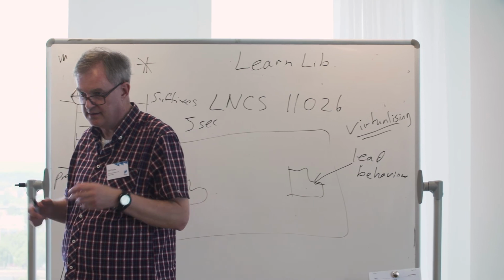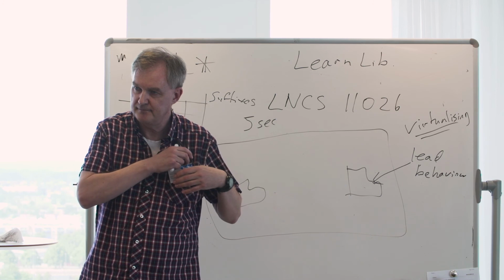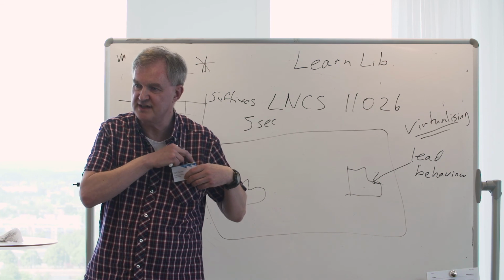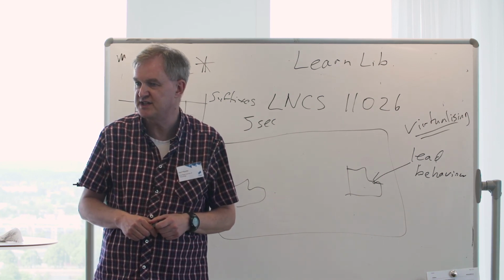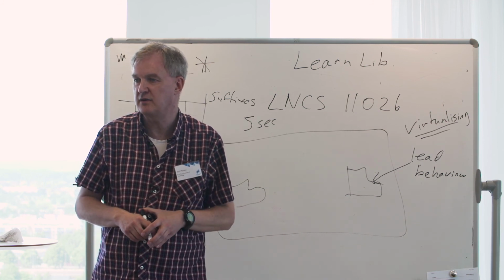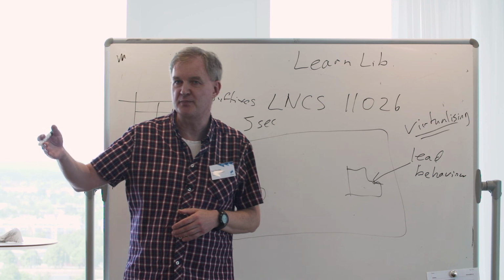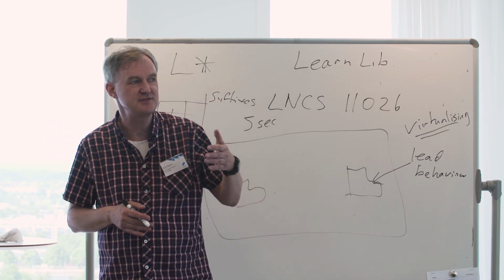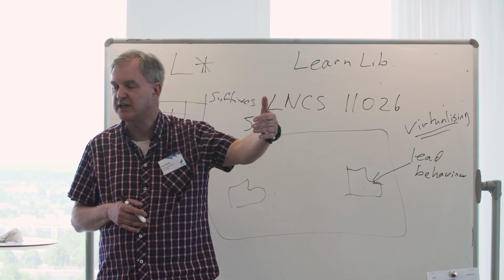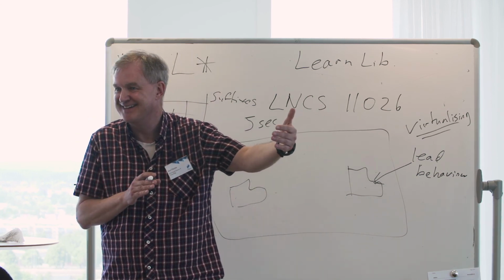The problem is that the algorithm for transmitting the positions was incorrect. Yes, I understand. So unless there's some redundancy in the situation that observes that and steps in, things will go wrong, of course. It will look static, and if it looks static, it will probably look a little bit like an emergency brake. But the protocol won't be activated, so instead the CACC algorithms will just observe. Well, will they observe? They've lost GPS. If they had radar, they could still observe that the vehicle in front was not moving. Otherwise, that's the end, right?